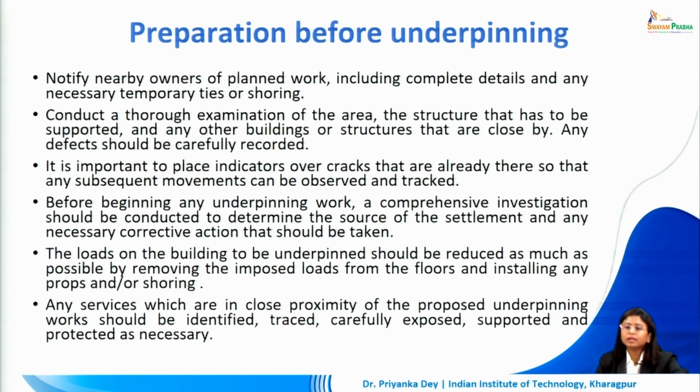So before we undertake this task of doing underpinning, there are certain preparatory practices, certain precautions we have to take. So first of all, we will definitely have to notify nearby owners, landowners, our neighbors about the planned work, and we give complete details about the task that is going to be done and what are the necessary temporary structures like shoring that have to be added on the external facade of our superstructure to ensure that the upper building is protected while we are changing anything underneath.